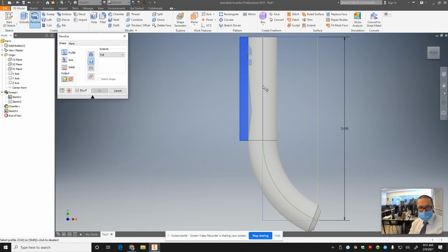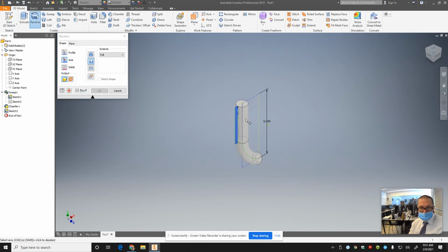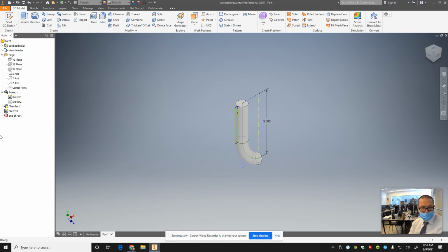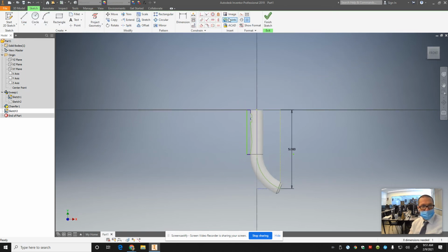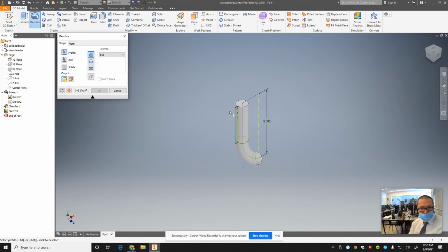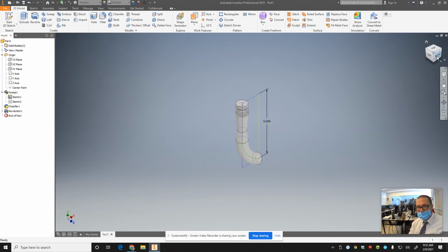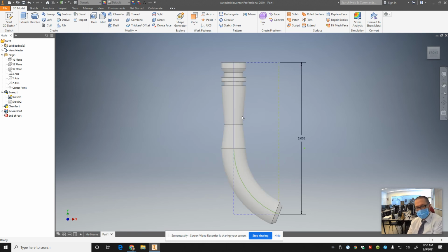Cut extrusion about that central axis. Now, oh, I have to put that in the same sketch. Okay. Back into sketch 3 one more time. I just got to draw a line in the middle here for it to revolve around. All right, now, there we go. Found the surface, axis, and it's going to be a cut. So I just cut off some of the material there. You know, and that's going to be up to you what you want to do there.